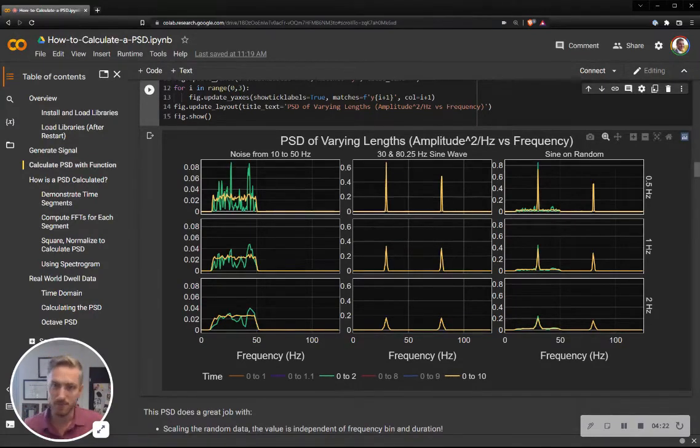So that's really good. Now, if I look at the sine dwells, you'll notice that as my bin width gets wider, so it goes 0.5 hertz to 1 hertz to 2 hertz, my value goes down. And that's because it's a density. As my area, if you will, is getting a wider frequency range, there's less frequency content spread across that whole wider range. But as I narrow in exactly on that sine dwell, it has a higher density of energy.